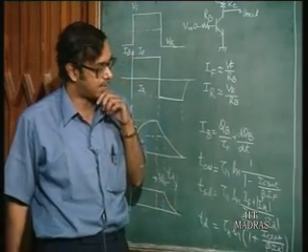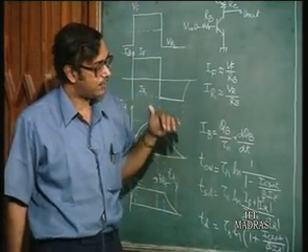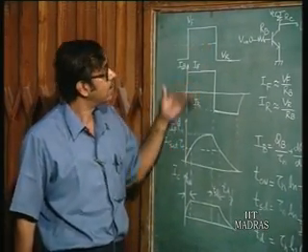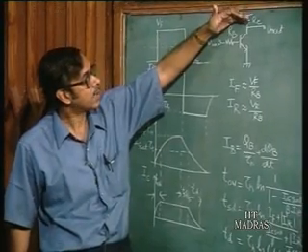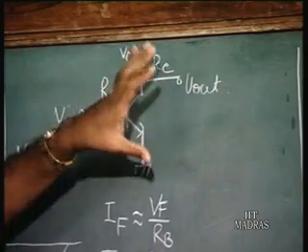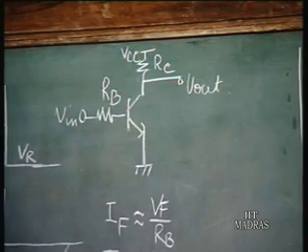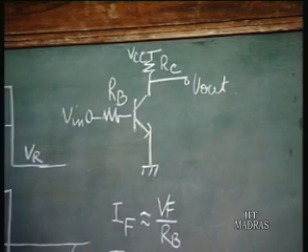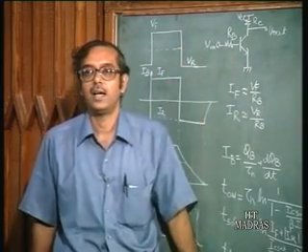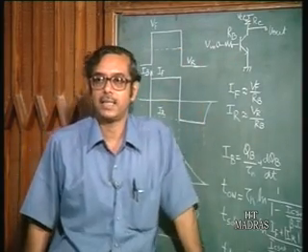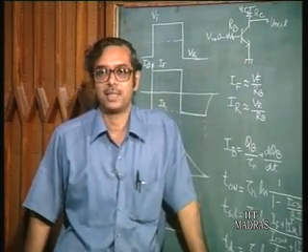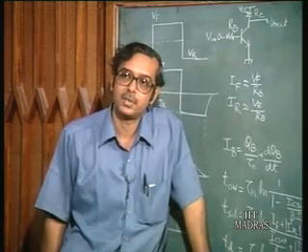Now, when you apply a forward voltage, the transistor output, the collector-emitter voltage, is going to drop as you go on increasing the base current, we have seen that, and when it reaches saturation, VCE becomes around 0.2 volts. But suppose you had a circuit by which, just when it was approaching saturation, the base charge storage would stop by some mechanism. That would be an ideal case.